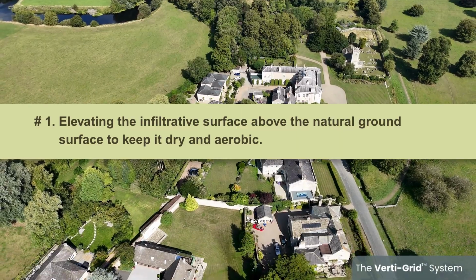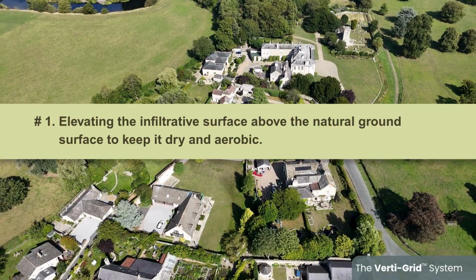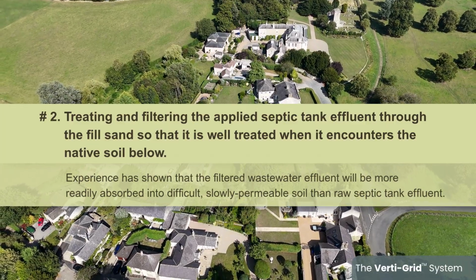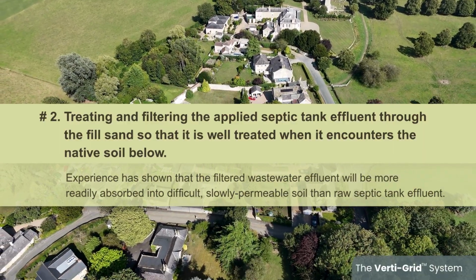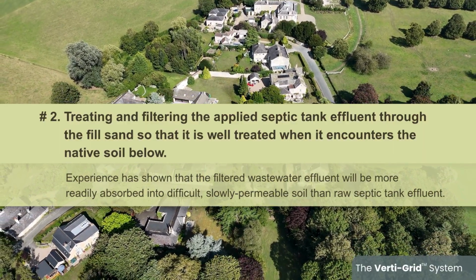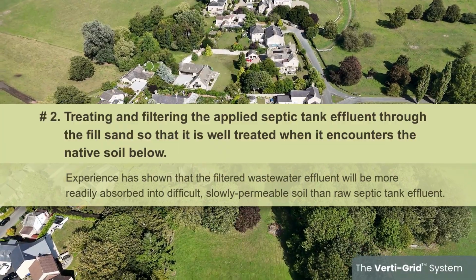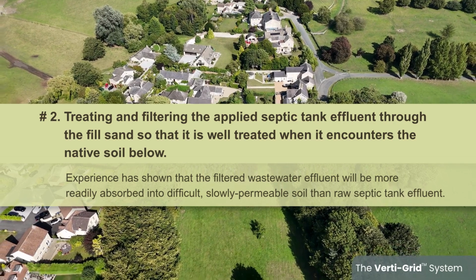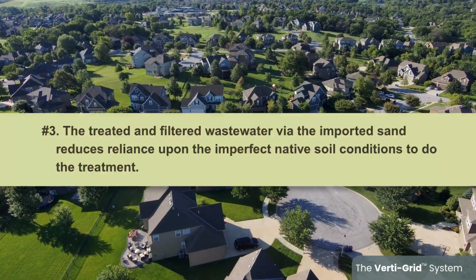Elevating the infiltrative surface above the natural ground surface to keep it dry and aerobic. 2. Treating and filtering the applied septic tank effluent through the fill sand so that it is well treated when it encounters the native soil below. Experience has shown that the filtered wastewater effluent will be more readily absorbed into difficult, slowly permeable soil than raw septic tank effluent. 3.